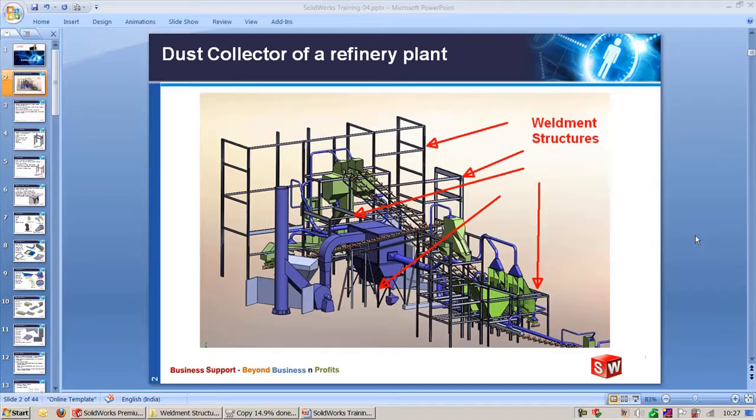What actually are we doing in weldment design? One, you are inserting the structural members on a 2D or 3D sketch. Based on that, you are constructing the additional structural members called the square beam or I section beam or C frame, according to the requirement. And based on this, finally the output we need is the part list. In simple terms, we can say how many structural members are required to complete this entire fabrication, plus what is the length for each structural member. These are the details you can get from weldment design.